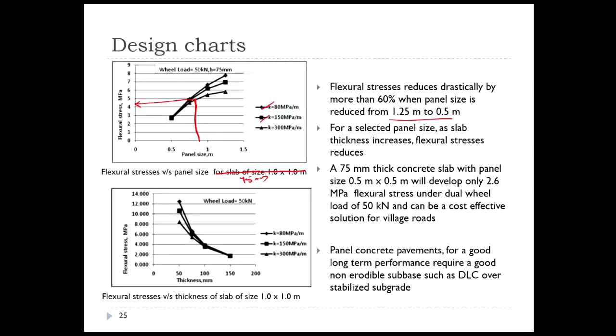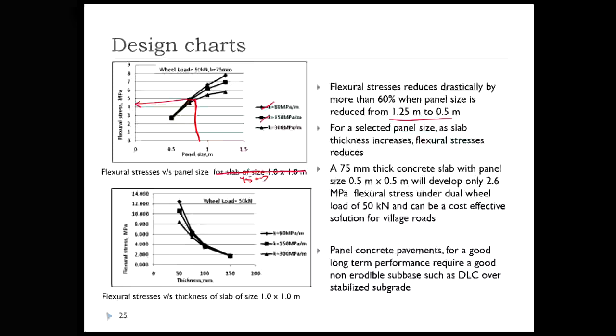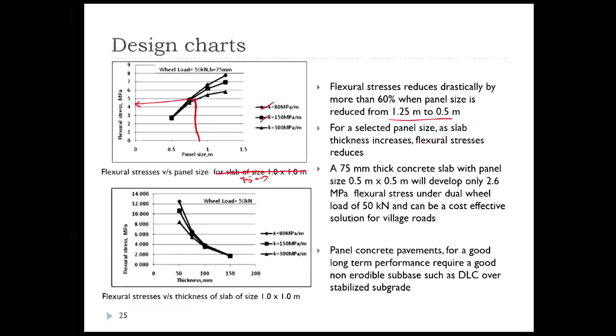Now, panel concrete will have long-term performance provided it is constructed above a non-erodable subbase, such as a dry lean concrete or a stabilized subbase layer.